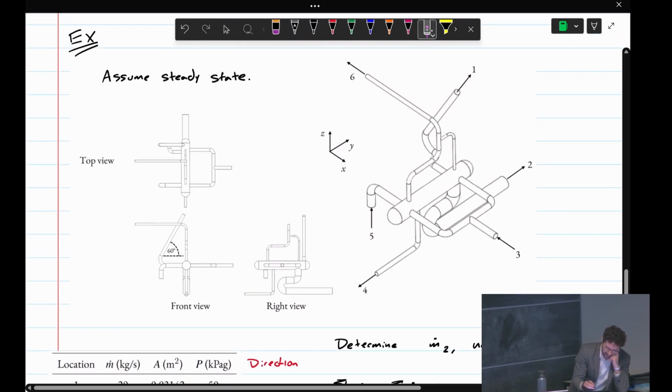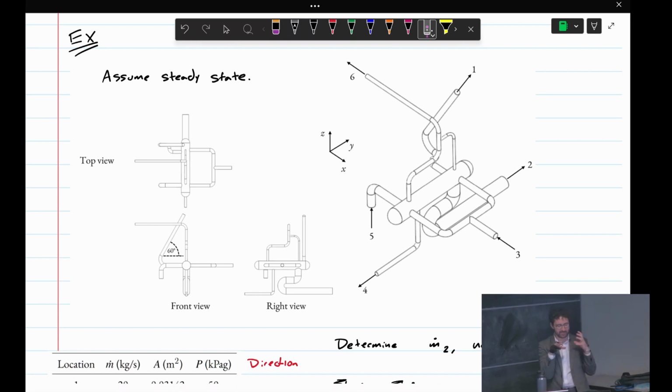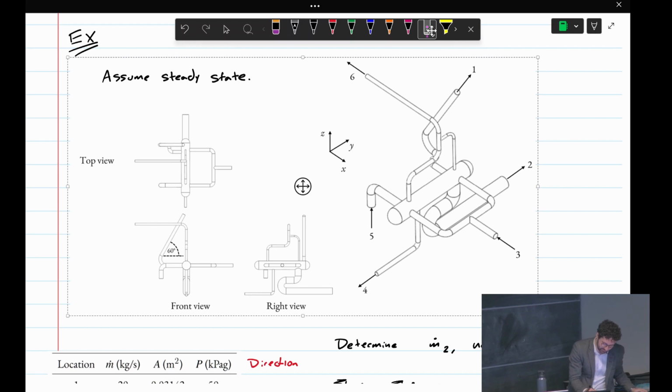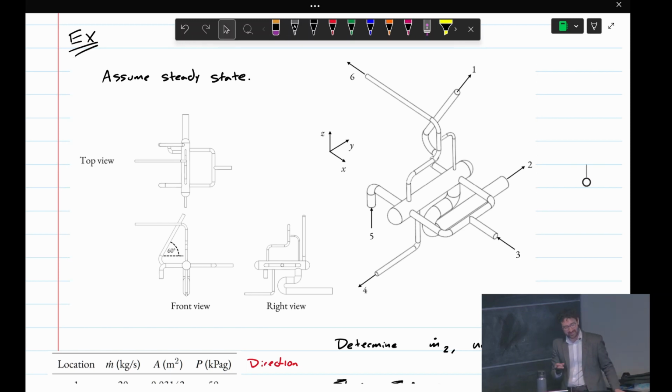Okay, so our control volume for this question, something I want to emphasize. Our control volume is sort of this bubble that hugs every single one of these pipes. That's going to be incredibly hard for me to draw. But you can think of it like the CAD operation where you do an offset from a surface and it puts it a little bit outside the surface. It's just like that operation over this whole pipe. The reason our control volume encompasses this pipe is that we want to determine the net forces on this pipe, and we can't neglect friction at the walls. So our pipe is part of the control volume because the forces applied to that pipe will be the forces on our control volume. Okay?